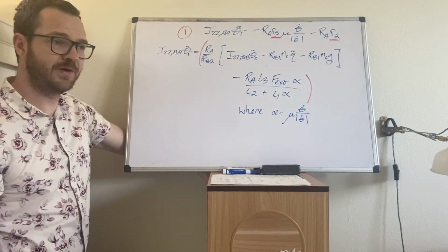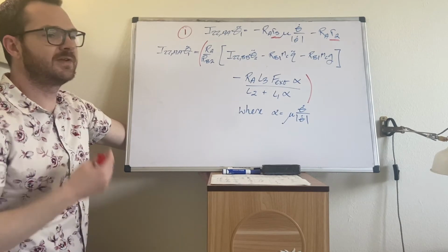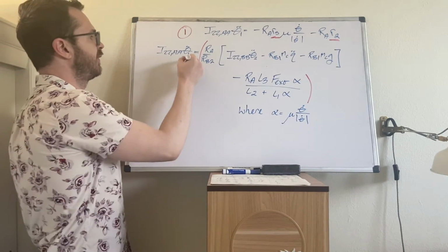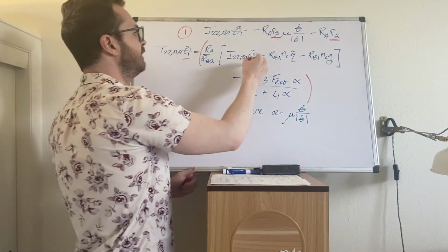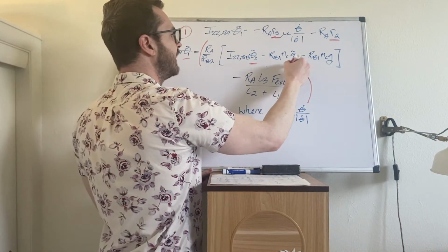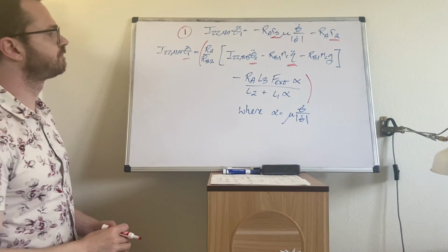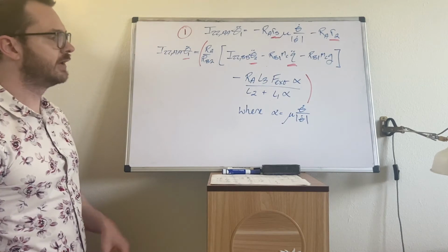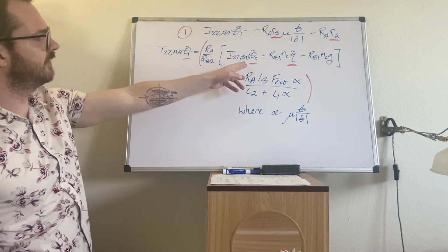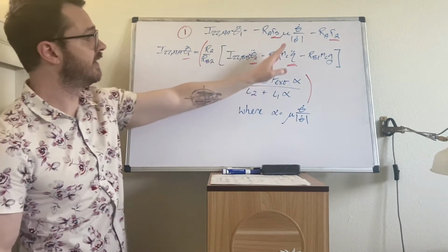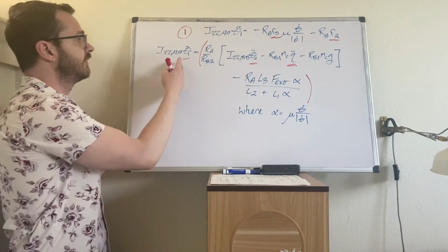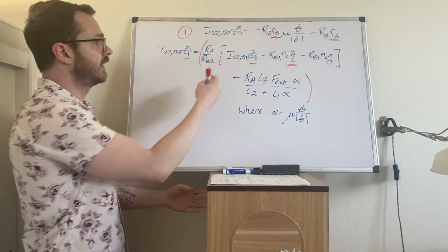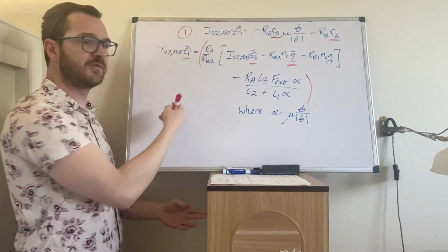So, are we finished? Well, what are we attempting to solve for? We want to solve for an acceleration. Well, this equation has 3 accelerations in it: theta 1 double dot, theta 2 double dot, q double dot. So what do we do? We only have one equation. We can only solve for one unknown. That means that we need to replace theta 2 double dot and q double dot with expressions of theta 1 double dot and then collect terms. So how do we do that? How do we solve for a generalized acceleration in terms of another generalized acceleration?